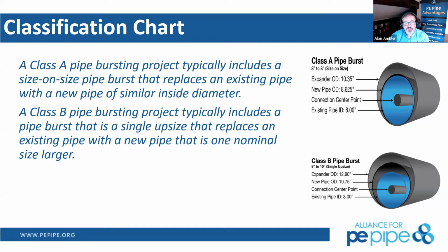So we had another question from Eric Lopez as well. Has there been any lessons learned on using static bursting for projects where the existing main is under buildings or under pavement concrete areas at shallow depth? With the deflection or the displacement of soils, which we'll talk about more in a minute, if we can control the pressure on top of that pipe, i.e. they can park a dump truck on it or something else with steel plates, sometimes we can force any soil displacement out instead of up. And then it also depends on soil conditions and the strength of that soil as well.